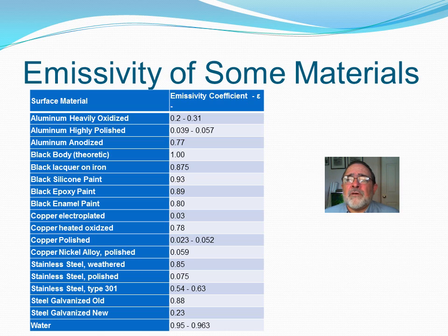Notice here the polished copper, and then what happens to it when it is heated and it oxidizes. A very critical issue to a thermographer, an issue that you're going to deal with when you're actually writing a report. Why do you need to cool off this copper contactor?